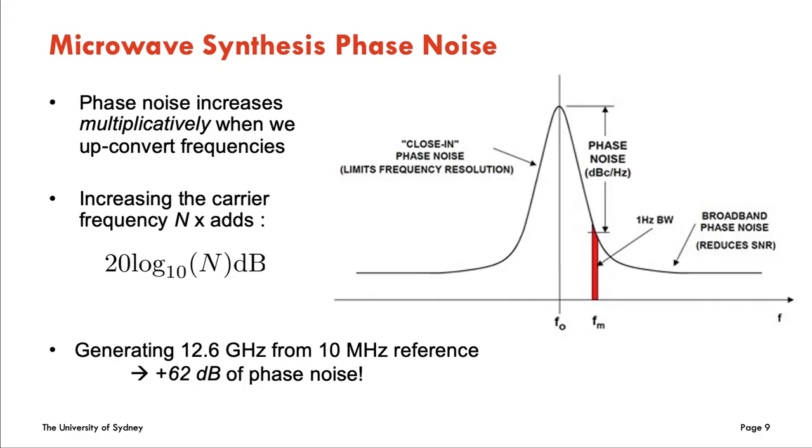Now, I just want to finish with another ongoing project to improve our microwave gate fidelities. In addition to control techniques like DCGs, we can also look at improving the purity of our microwave control field source. Currently, we use an IQ modulated Keysight vector signal generator, which is locked to a 10 MHz reference generated by a rubidium atomic source.